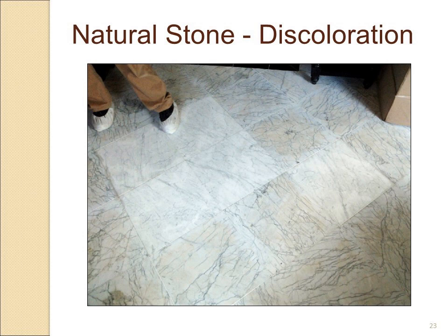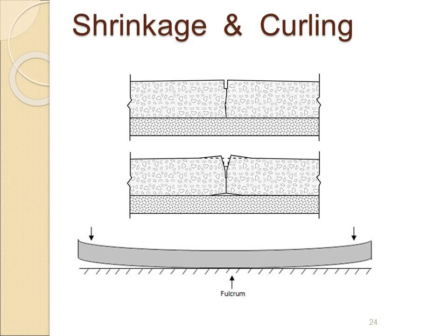So again, it's a situation where none of us want to be in, but obviously this could happen, and it's all because of moisture. And moisture has so many effects that could be damaging to tile and stone that we need to be aware of them and consider them. For example, substrates move because of moisture. We all know that when concrete is first placed, the surface of the concrete dries out faster than the underside. So when the top side dries out, it tends to curl upward.